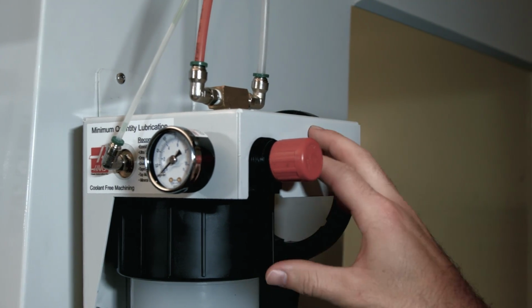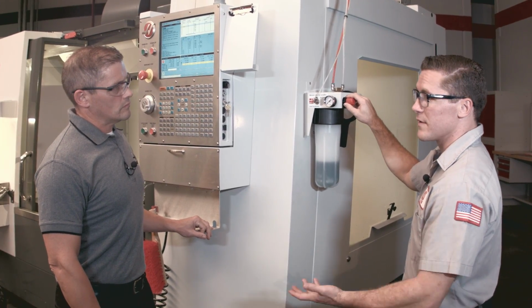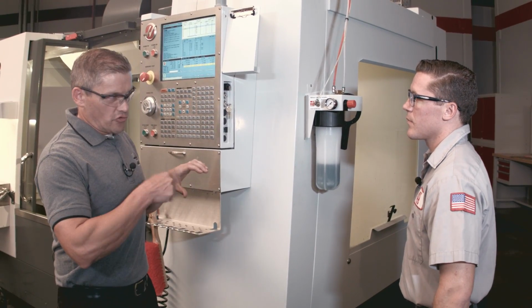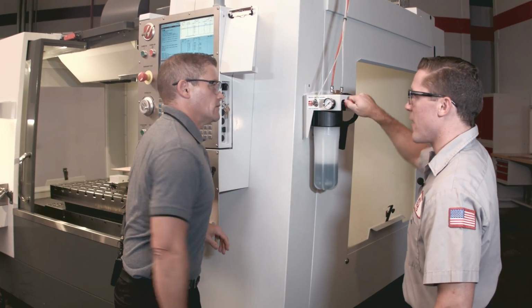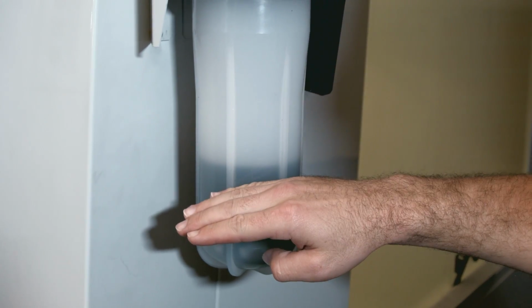And what's really great about this is I'm able to fine-tune the amount of oil that's being delivered to my tool. So basically at the nozzle, your atomizer screw, that's kind of your coarse adjustment, and then this is your fine adjustment. Yeah, right, this is my fine adjustment here. And what's really nice, we've put this in a location that's easy to view, easy to access. Every day I can walk up and check the amount of cutting fluid that's in the reservoir. If I need to make an adjustment, it's all right here.